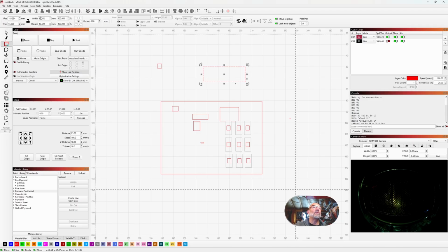But say you wanted to say, oh, I need to have the width of this at 20 millimeters. I hit 20. And I need the height to be 10. There you go. So that's how you can adjust that. And if you say, oh, you know what? The directions told me instead of 20 millimeters, I need to go up to 120%. So you hit 120% and it increases to 24. Now again, if you needed 20, you go back over here at 20.